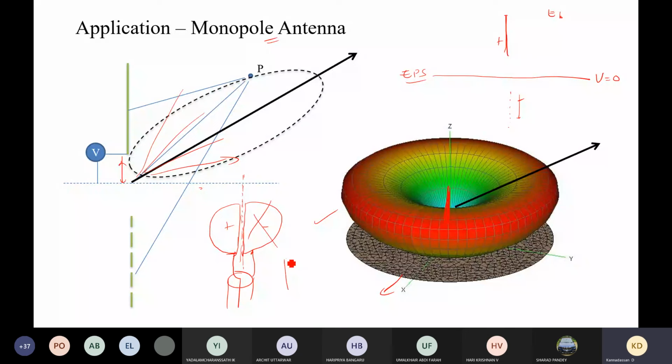And let's say I have to solve for a particular problem like this. Okay, so this is carrying a current, and I have to calculate the electric field due to this plate. So what people used to do is they will put a line of symmetry, and this line of symmetry they will call the equipotential, or simply they will keep this equal to 0. Then this simply gives the corresponding charge distributions, whatever it is. It will take the image of it and it will calculate it. So we can reduce the computational burden into half because of that.